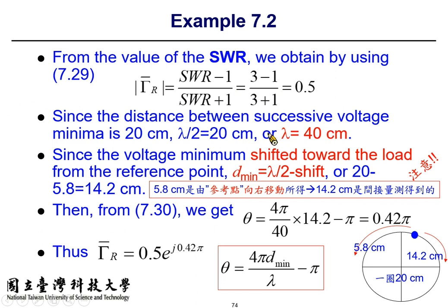But what you can do is move the probe back and forth and check the location for maximum voltage and minimum voltage, and record the voltage you find on the oscilloscope. For example, in this example, the maximum voltage is about 3 times the minimum voltage.